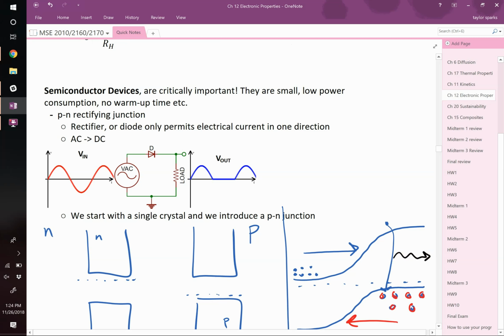This is an LED. An LED gives off a light of a very specific color, right? How does it do that? They chose a material that has a band gap, which equals, in energy, the color of light that you want to get out. And then they intentionally drive current up this energy hill and allow these things to fall back down and occupy these, right? Or conversely, you could imagine a hole going this way. Since it's a hole, sort of the opposite, this is actually going down in energy for it. Electrons are easier to think of, right? You created an LED.